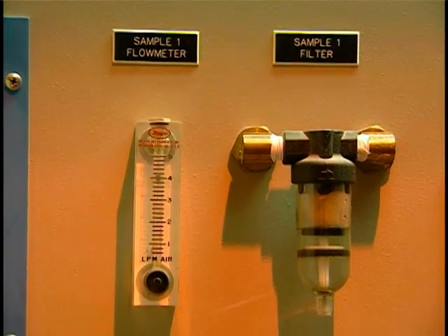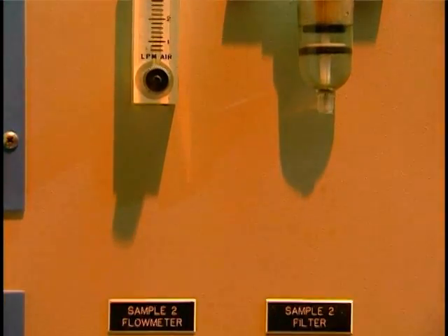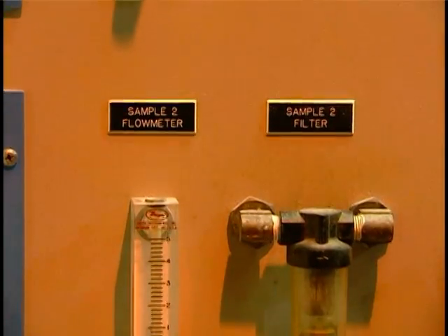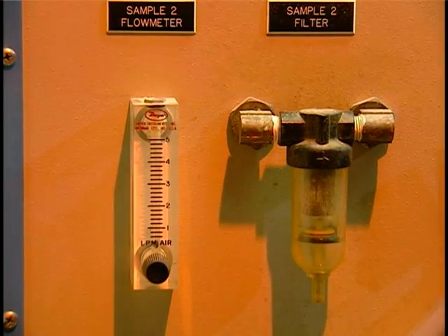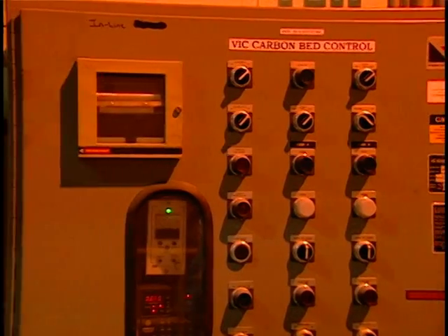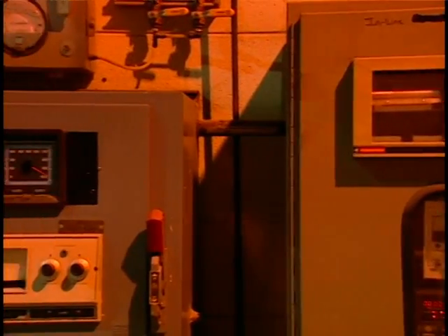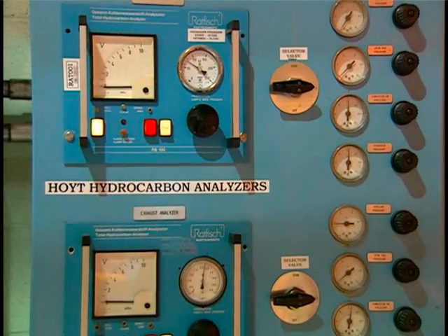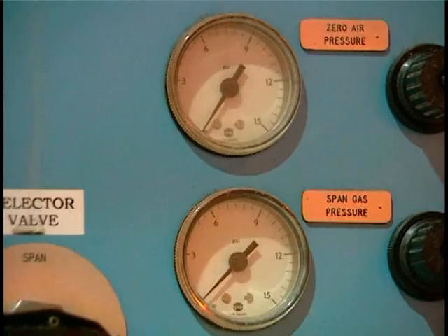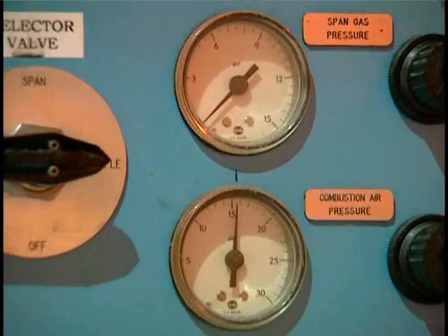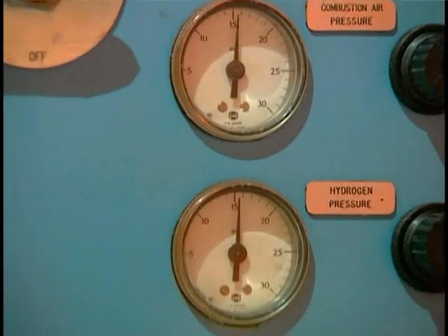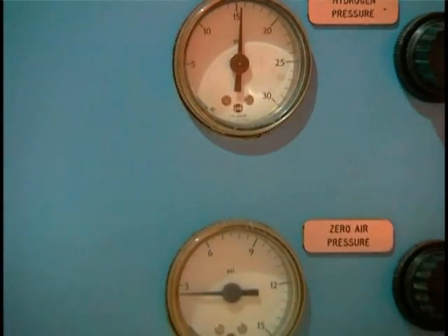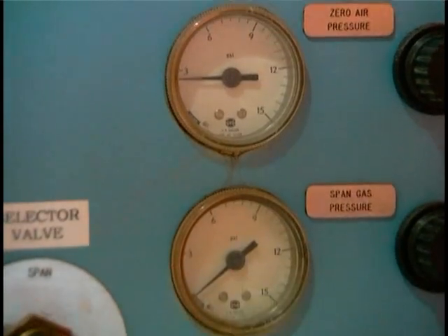This would include an inspection of the condition and integrity of the sampling system and a check of the sample gas flow rate. In addition, the calibration frequencies and procedures in the maintenance records for the instrument should be checked. Calibration should be performed on a daily basis using a calibration gas cylinder that is less than 6 months old and has a pressure of at least 150 psig.